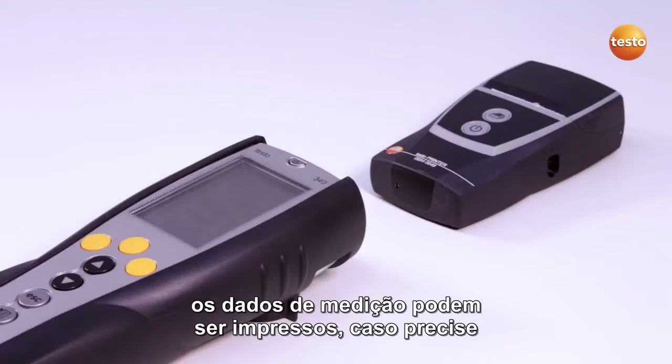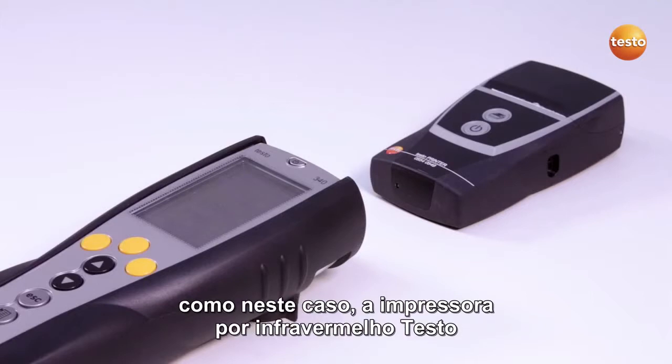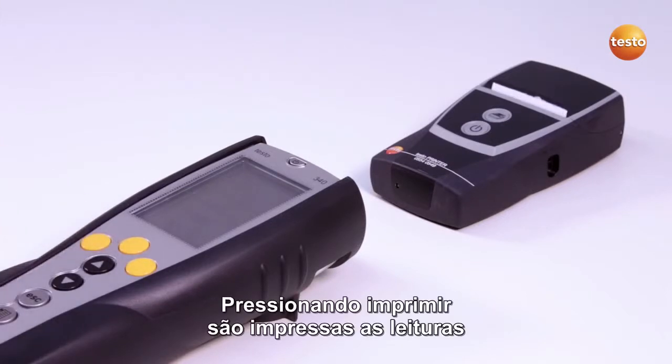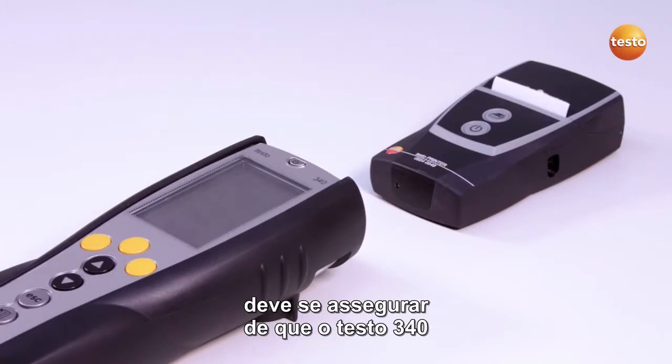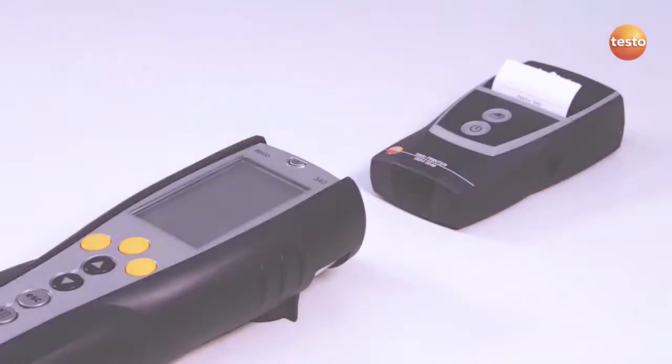The measurement data can be printed out if required. Use either the Testo Bluetooth printer or, as in this case, the Testo infrared printer. Press to print out the readings. Make sure that the Testo 340 is in the direct line of sight of the infrared printer.